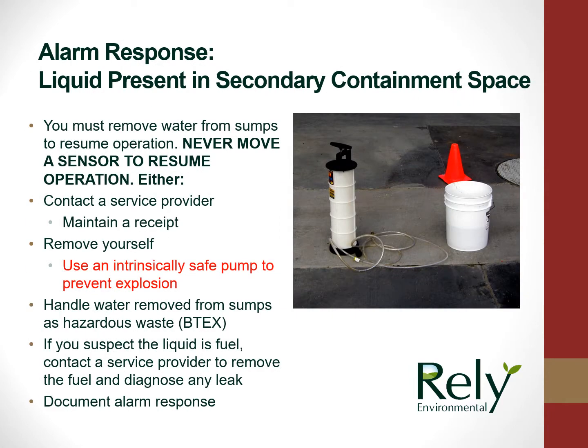If an alarm shows that there is liquid in one of the secondary containment spaces, you can either contact a service provider and maintain the receipt, or you can remove it yourself. Make sure to use an intrinsically safe pump to prevent a fire or explosion. Handle waste removed from sumps as hazardous waste. If you suspect the liquid is fuel, contact the service provider to remove the fuel and diagnose any leak. And make sure to document the alarm response.